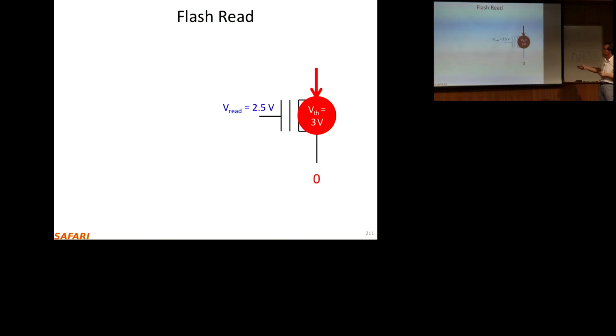If the read voltage is smaller than the threshold voltage of the cell, then you inhibit whatever is passing. So the switch is off, basically, in that case. And how do you determine the threshold voltage? By programming. If a cell is programmed to 0, 0, its threshold voltage is smaller. If a cell is programmed to 1, 0, its threshold voltage is higher. So threshold voltage is programmable, and that's exactly how you store the data. Data is stored in terms of threshold voltage.